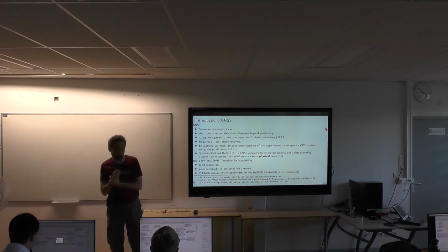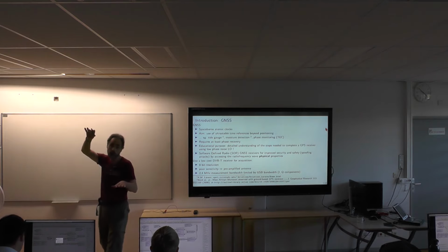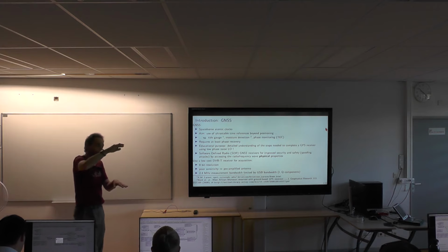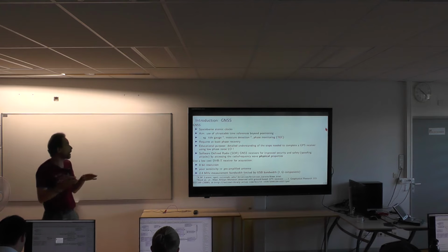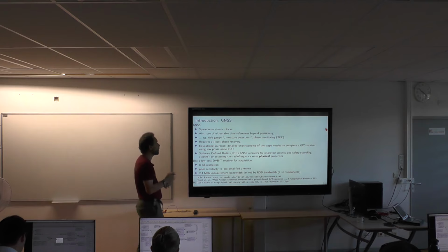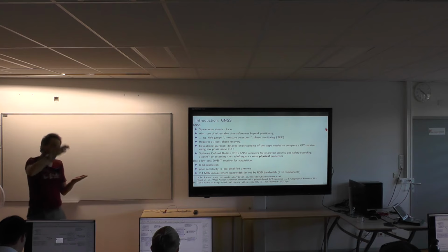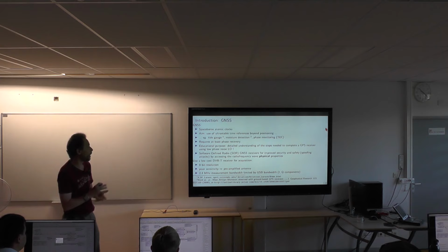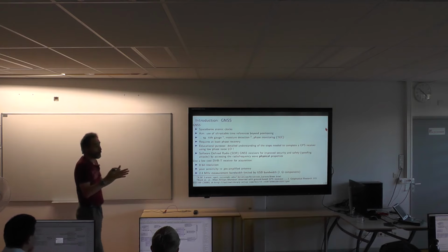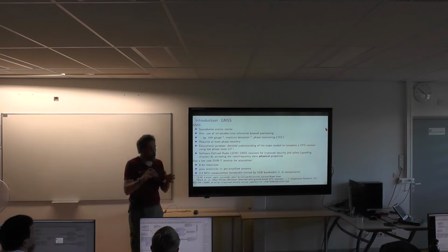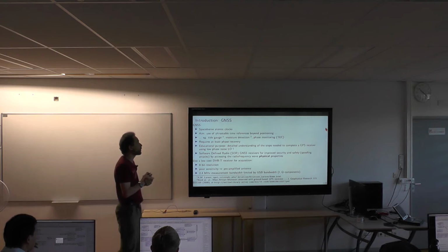In past developments, there has been some work on how you can time the difference between the direct wave reaching the antenna and the wave bouncing over, for example, a body of water, and that allows you to make a tide gauge using the time delay difference between the direct wave and the reflected wave. There are people working on analyzing the amplitude difference between the direct wave and the reflected wave, and because the reflection intensity is related to moisture in the soil, you can make some moisture detection. One of the outputs of GNSS is an estimate of ionospheric ionization plasma level, called total electron content, the TEC output.